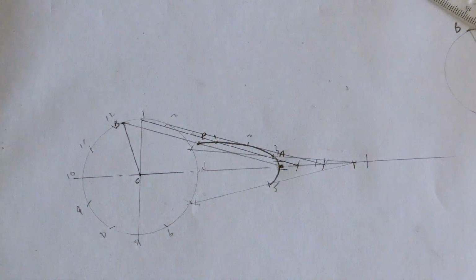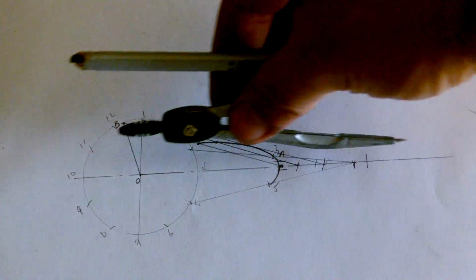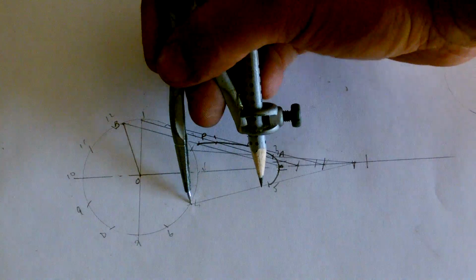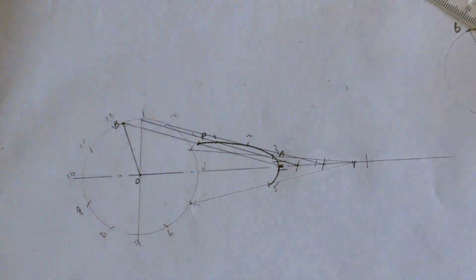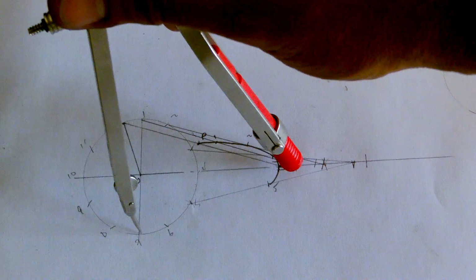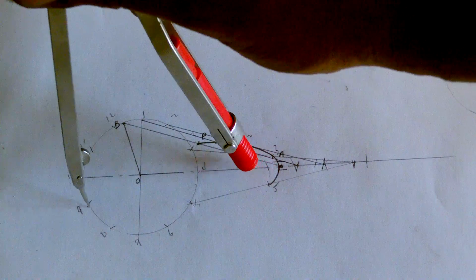That's my locus so far. Now since this line, the slider, is in line with the center, this is going to be a symmetrical locus. So each point I'm taking from the bottom part of the circle is going to coincide with the previous points I took to get a symmetrical locus.